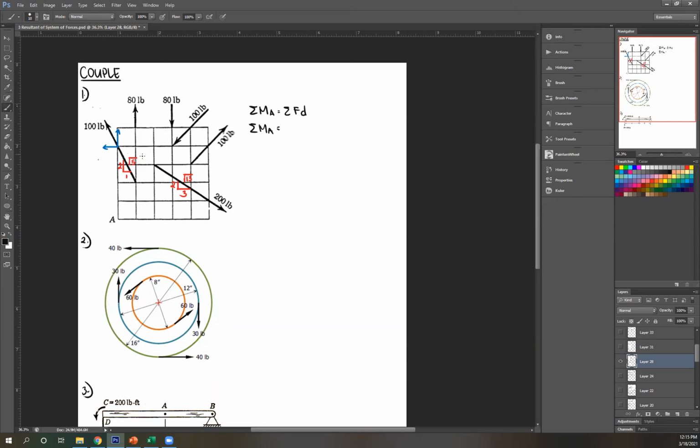Going back again, using this, it's the horizontal component of your 100. To get the horizontal component, just write the force multiplied by the side that is parallel to your force. So it's 1 over hypotenuse square root of 5. And then, don't forget your sign. Rotate it about A. This is counterclockwise, so therefore that should be negative.